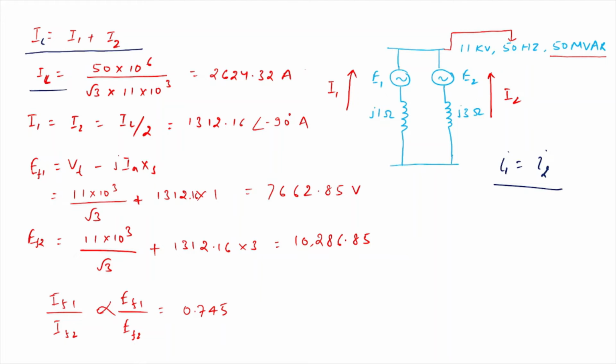It is supplied, and whatever supply, it is acting as condensers, and to the load it will be lagging current. So whenever any machines, condensers, capacitors are supplying reactive power, they supply lagging current. They absorb leading power, but they supply lagging power. That is the property of a condenser.